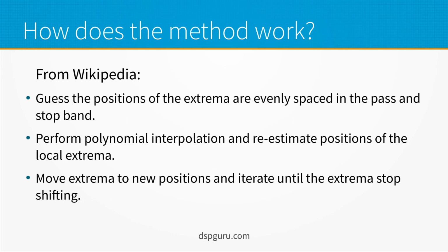But some key points to think about: it's making a guess in the frequency domain about the contents of each pass band and stop band. It does an iteration to evaluate the errors that result from the guess. It improves the guess using something called the Remez exchange algorithm. And that's why this method is sometimes called the Remez method, kind of incorrectly.